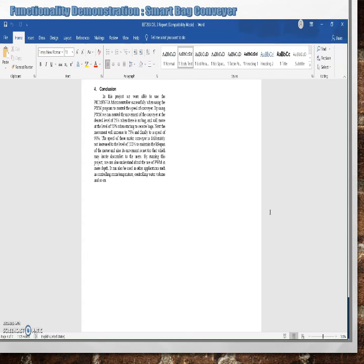By using PWM, we can control the movement of the conveyor at the desired levels of 25%, 50%, 75%, and lastly 95%. The speed of this motor conveyor is deliberately not increased to 95% or 100% to maintain the lifespan of the motor, because it will affect our board and our programming,